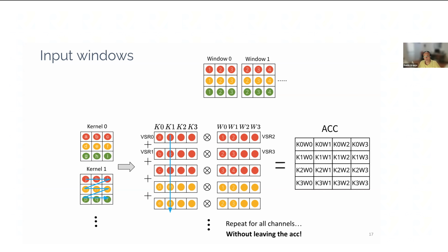What actually happens is a packing step before you do this. You load the vector registers. Now that vector register 0 is loaded and vector register 2 is loaded, I do the outer product. And there are many design points for that in terms of hardware. You could have an inner product based systolic array approach, which takes 3n minus 2, where n is one of the dimensions of the input matrix.